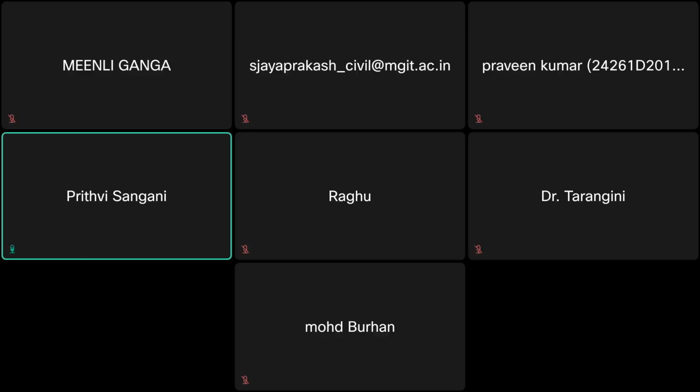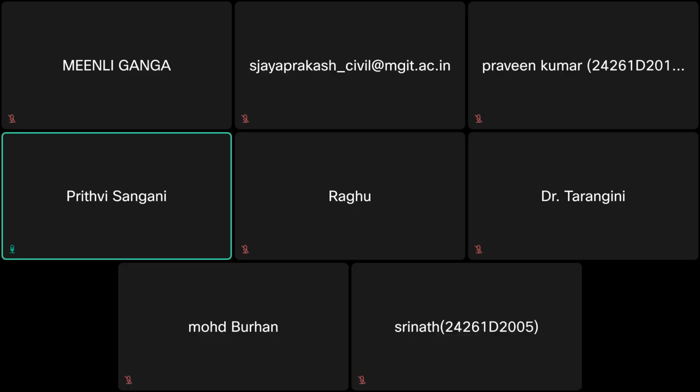Let me discuss something. This is the load testing of a railway underbridge that we have done using the concepts we learned in our UG, mostly in the BTech. We have these ILDs, influence line diagrams, from which we try to find the maximum bending moment, the absolute maximum bending moment, and the absolute shear force. So this is like a real scenario where we used those concepts which we learned in UG.